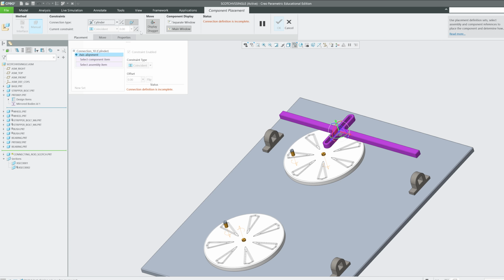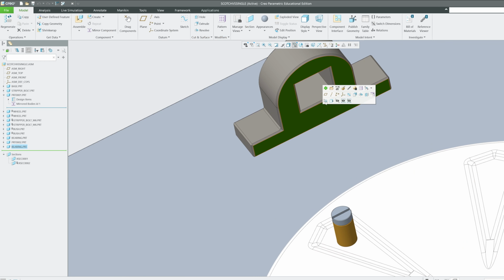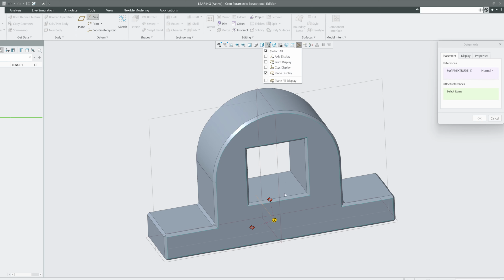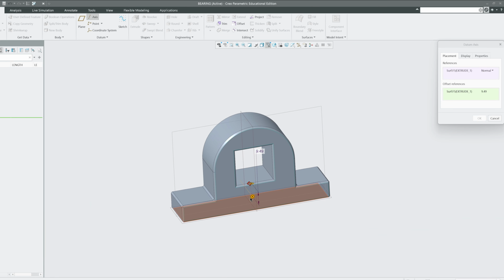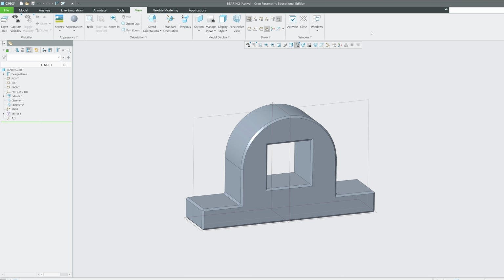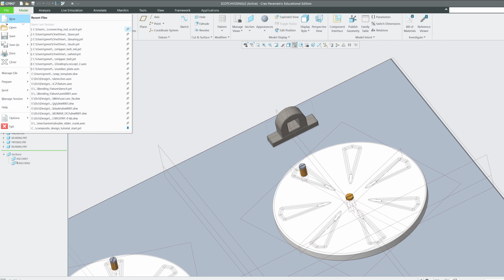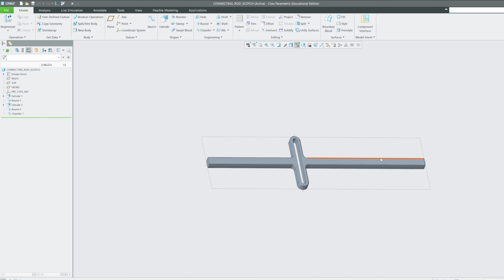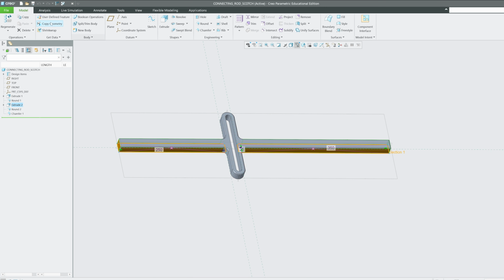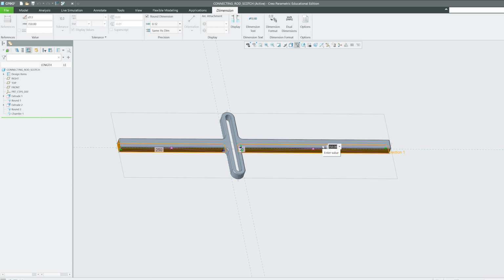So for the time being, I'm going to keep it like cancel. Let's create an axis. And of course this axis can be here and the center. So let's make center as 0, and let's make the distance also as 0. Now let's click OK. Now same I need to do with another part, which is our rod, and of course we need to increase the length of it as well. So let's increase the length actually first. I'm gonna make it like 500.